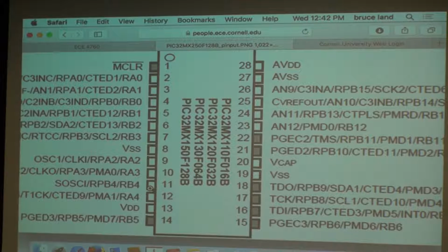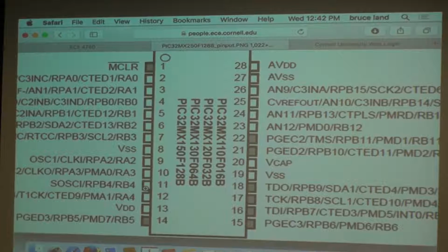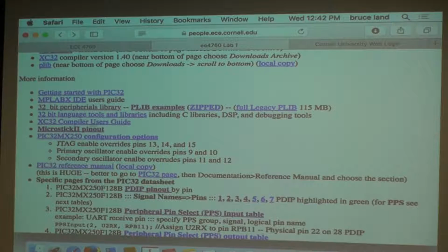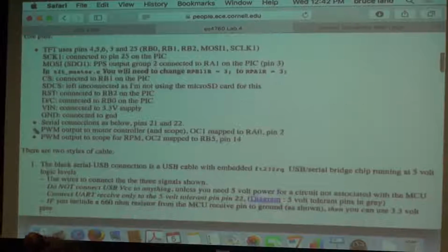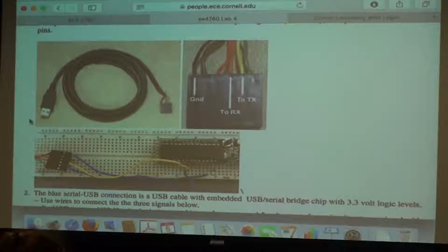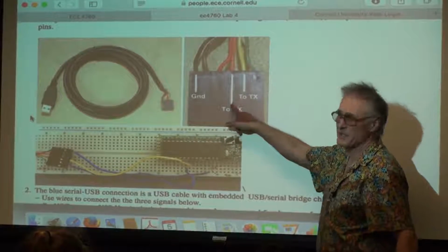And that matters because of the two kinds of adapter cables we have. One of them is a 5-volt system, left over from the bad old days of AVR. So this produces a 5-volt signal, and so you must run these to pins 21 and 22.